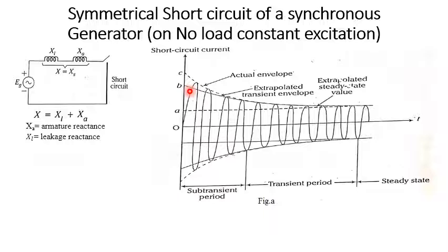This will be different in each phase and is accounted for separately on an empirical basis. Usually the multiplication factor will be around 1.6. This figure shows the trace of the armature current when neglecting the DC offset current. This current will be similar in all three phases except for a phase angle difference of 120 electrical degrees. So this is what we can see.